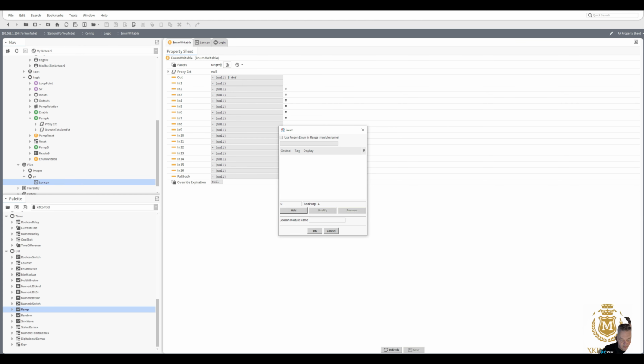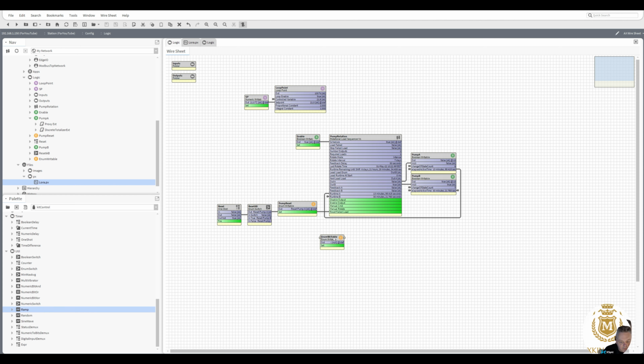So I'll just put reset there, reset pump A. Now I know we jumped to 2 to reset pump B, and if there was any more it would be a 3 to reset pump C, and so on, a 4 to reset pump D. But we're only doing A and B, but I'll just add them in there anyway. Okay, save, back out, actions, set, and then you can select what you want. So we'll leave it at A, and that's all I've just done here with that particular one.